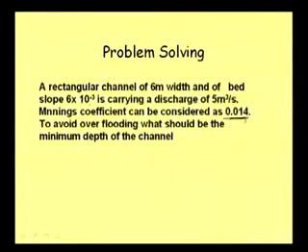still for our computational purpose we assume some value, and Manning's coefficient can be considered as, say, 0.014, which is given for this particular problem. And the question is: to avoid over flooding, what should be the minimum depth of the channel?